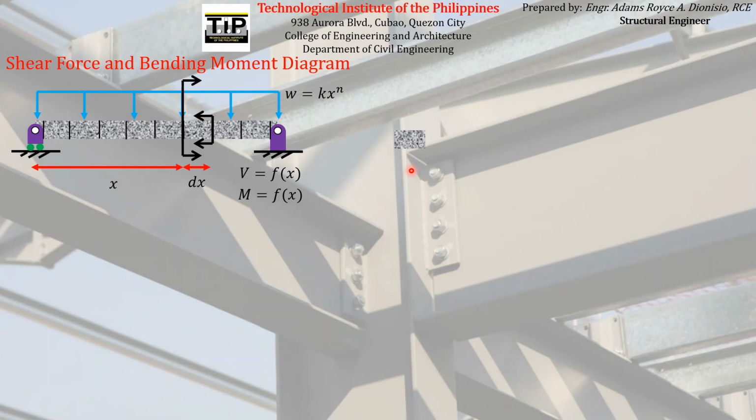So we know that every time we draw a free body diagram, we just put the external forces acting on the body. So what are the external forces acting on the body? First thing is the load applied to the beam, but it only carries the portion of the load from this point to this point. So let's call that again W. And what else? What are the other forces acting on this body? Obviously, the internal forces acting on this side and this side. And actually, those internal forces are what we call shear force and bending moment, like this.